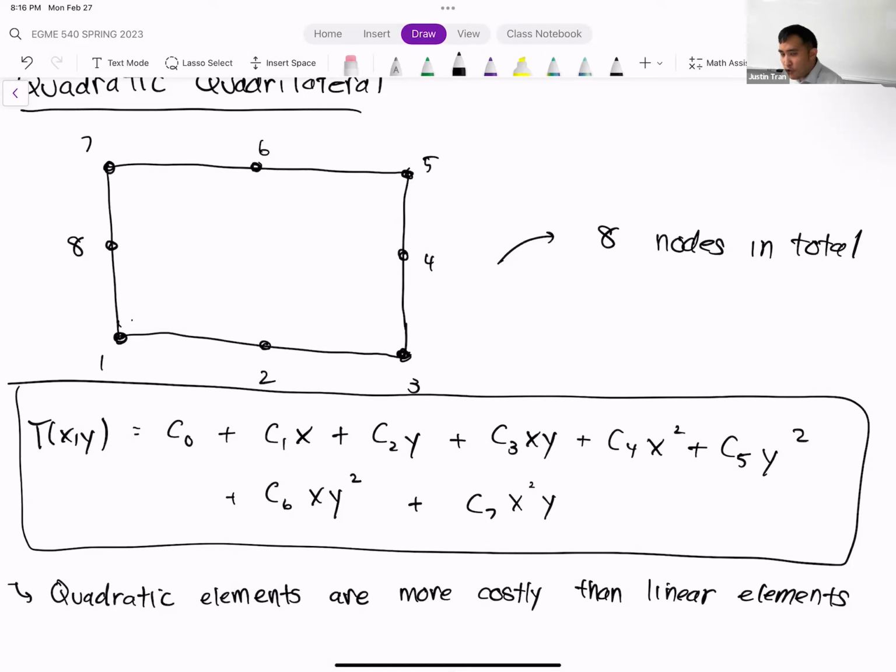If you look back to activity 1, Design Modeler was the first program that we opened. That's the one where you can actually set the dimensions of different parts. So basically, you change the dimension, and then you open up Mechanical again, and then you remesh and do all that stuff. You shouldn't have to remake the geometry, but if you open up that geometry in Design Modeler, you should be able to modify it. Yeah, I can show you really quick.